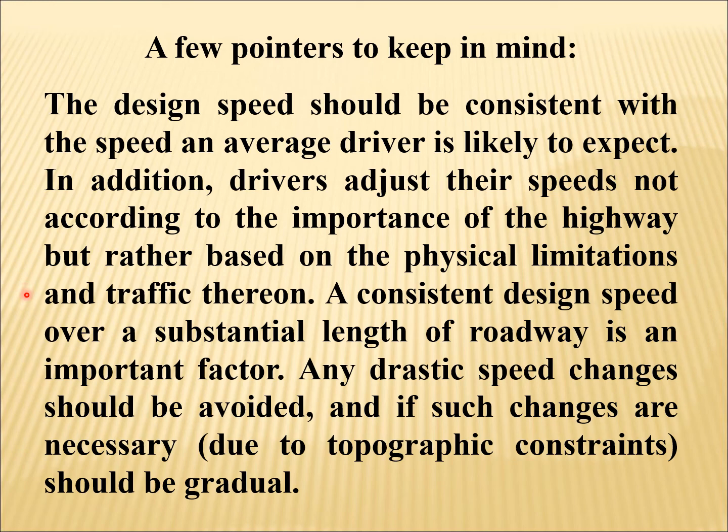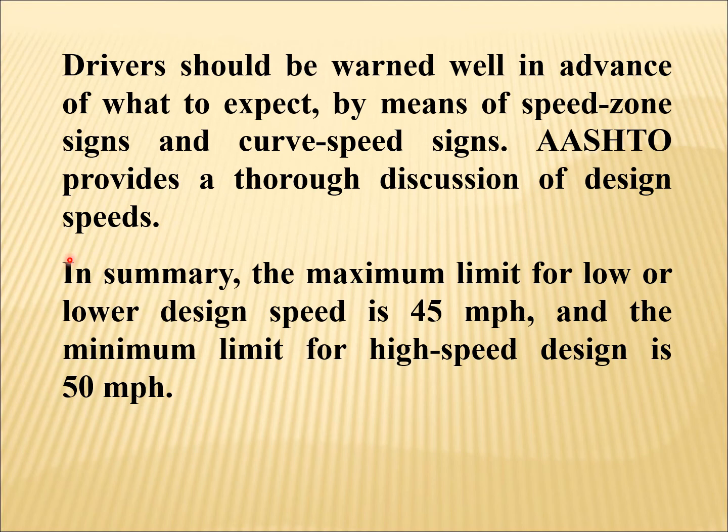A consistent design speed over a substantial length of roadway is an important factor. Any drastic speed changes should be avoided, and if such changes are necessary due to topographic constraints, should be gradual. Drivers should be warned well in advance of what to expect by means of speed zone signs and curb speed signs.